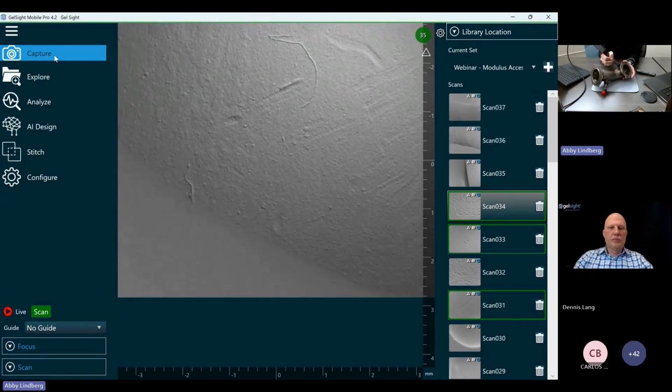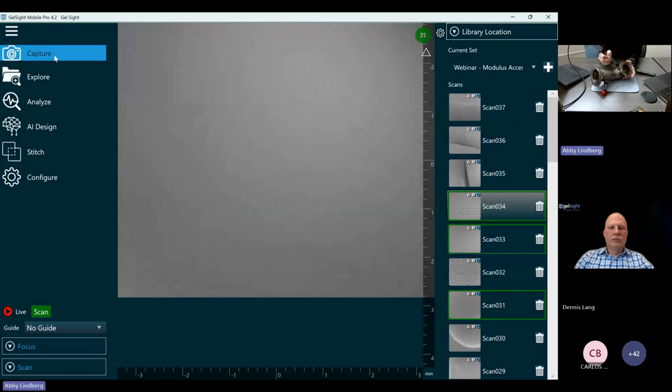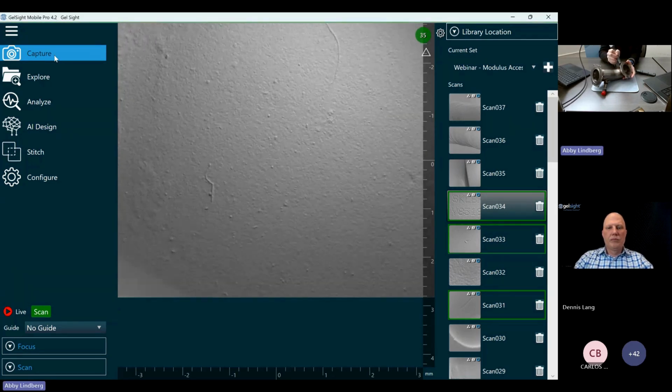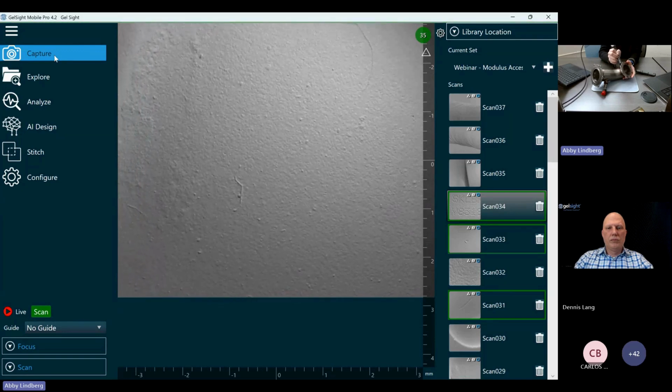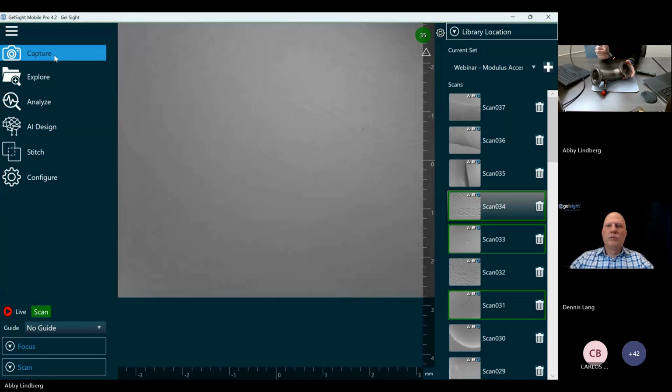We've got a bunch of miscellaneous scratches on this part here, or potential corrosion in some of these areas too, maybe some early corrosion right there. But now if I want to access the inside of this, we're just going to switch over to the 90-degree lens. And to do that, you mentioned hot swappable, so we'll watch that now.